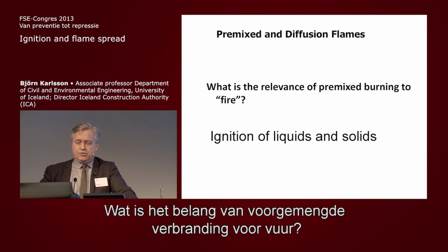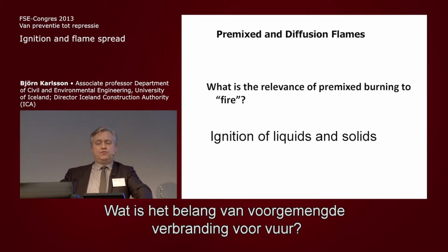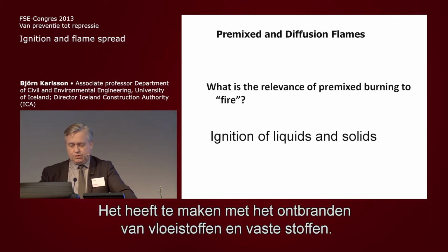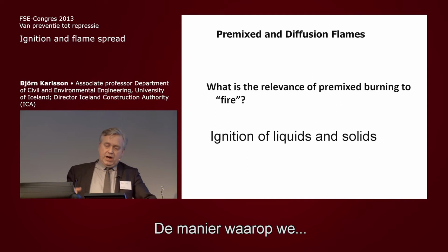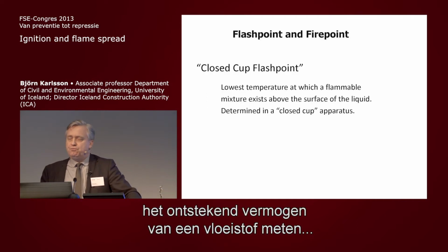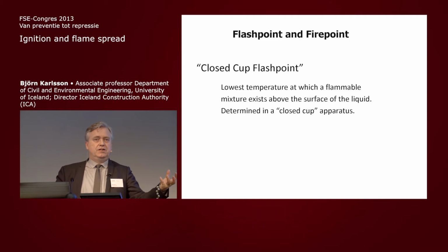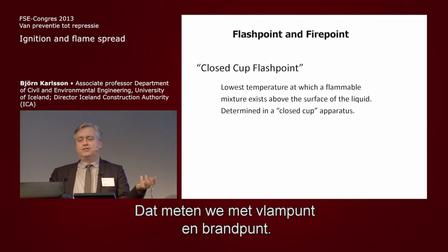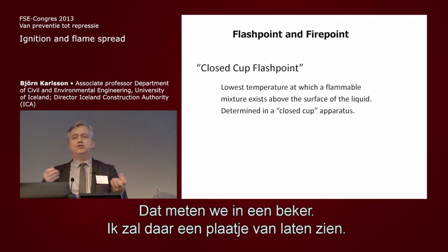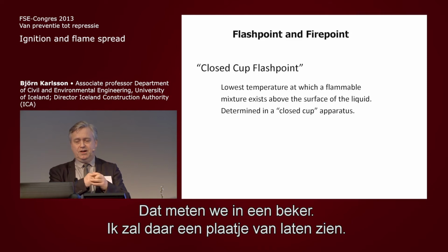So what's the relevance of premix burning to fire? It has to do with ignition of liquids and solids, and we're going to talk about that. Now, the way we measure the ignition propensity of a liquid is called flash point or fire point, and we measure it in a cup. I'm going to show you a picture of this.